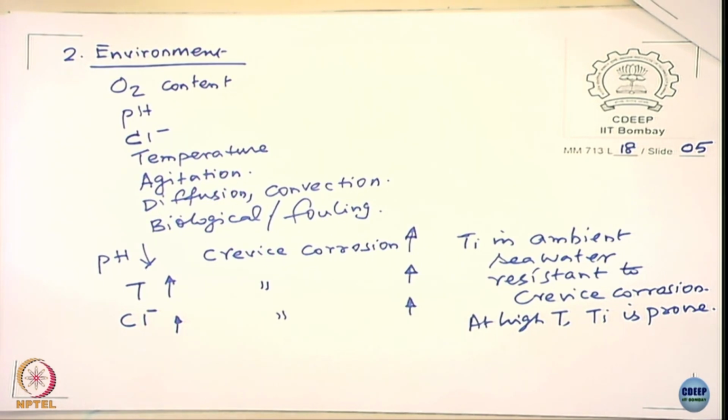Essentially, in the crevice, if you are able to make the metal passive, very stable, then what happens? You may have differential aeration, but still you will not get crevice corrosion at all, right. So the crevice corrosion also depends upon, in addition to deaeration and all, whether the metal can be made inherently resistant to corrosion, then the crevice corrosion resistance can be very high, possible to do that, okay. So, that is why the metallurgy is being developed actually, okay.